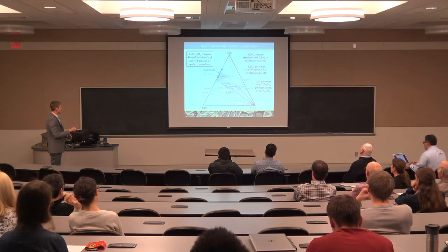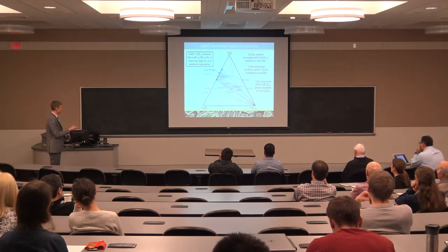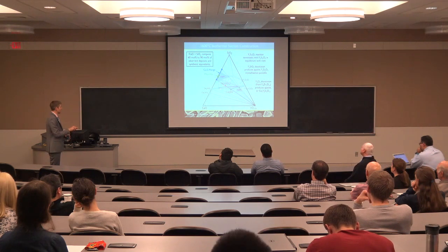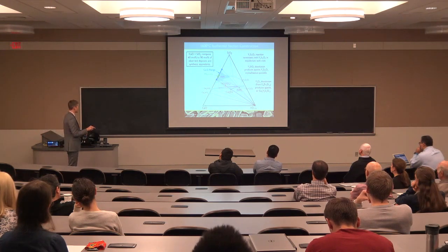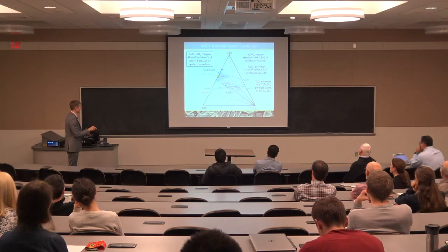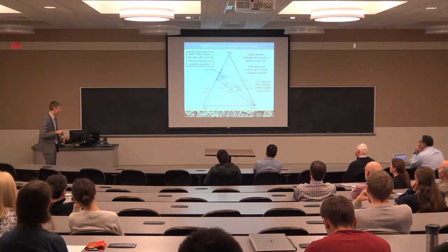And finally, if we have an yttria source from a yttrium zirconate coating, again, we expect most of the relevant range of deposit would first fall into this apatite field, but if we had a really calcium-rich deposit, we might instead form this silica-carbonate phase. And then the crystallization kinetics of these 2 phases are different, and so if we are in a regime where we form this phase instead of this phase, the mitigation strategy doesn't work as well because this phase is much slower to nucleate and grow.